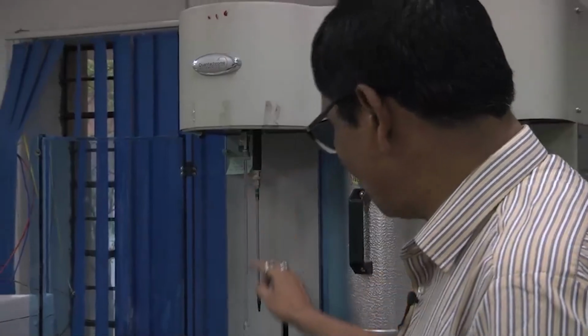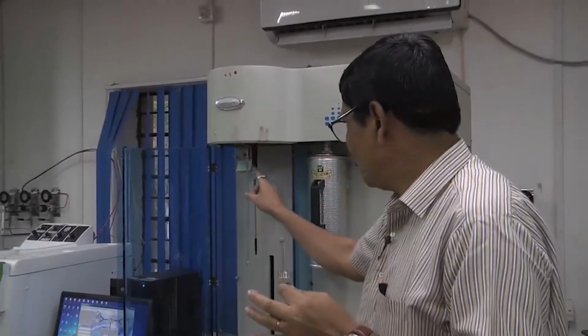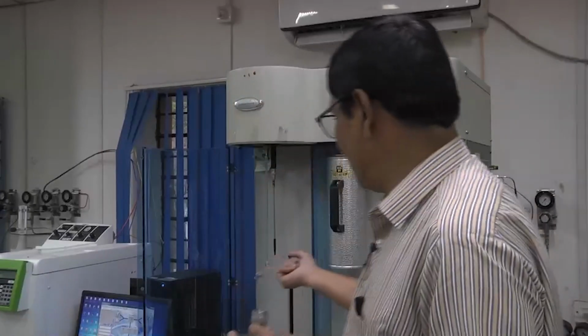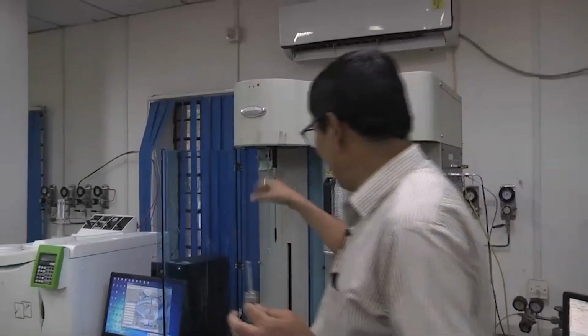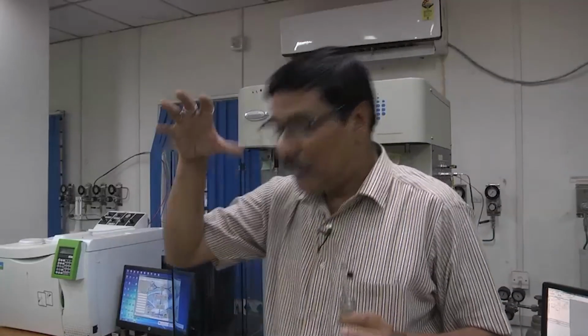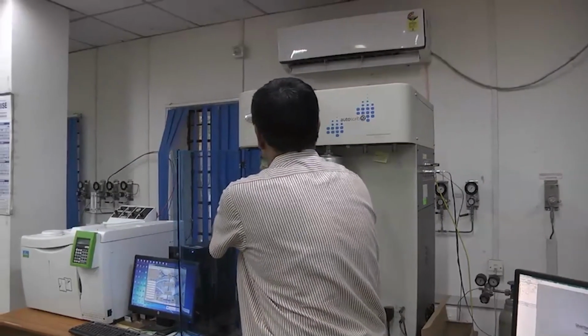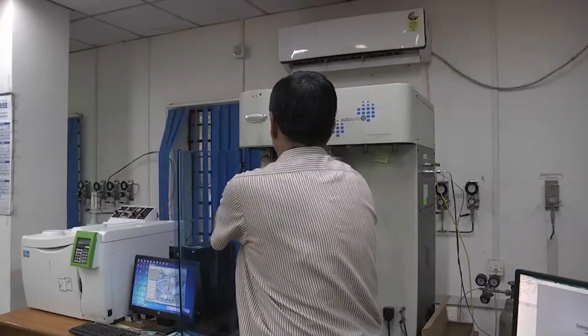Now, this tube, which is almost like this 6 mm sample cell, is called the P0 tube. The function of the P0 tube is to measure the pressure around and inside here. You can use this P0 tube, otherwise you can put in the atmospheric pressure at the place where you are measuring, say around 760 mm of Hg. Okay. Now, you have to put the sample after degassing into the 3rd port.